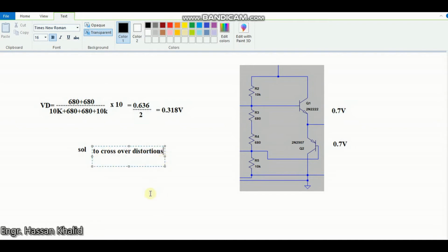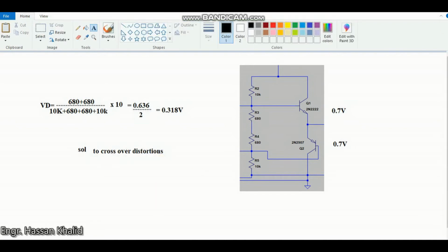So we have two methods that could do that. Now we have come to the point where we can propose the solution to this problem. One method is to change the internal resistance of R3 and R4 in such a way that the voltage across these resistors could sum up to such a value that each transistor can share approximately 0.6 volt, so that their base to emitter junction could enter the conduction state very slightly.